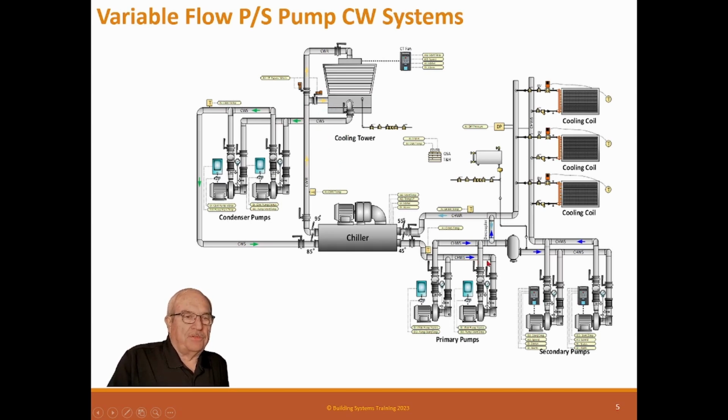Okay, on the evaporator side, so we have the field, the coils, the loads, and you notice these loads have two-way valves on them, and they're designed to variable flow. So this coil can have from 0 flow to 100% flow, as all of them can.